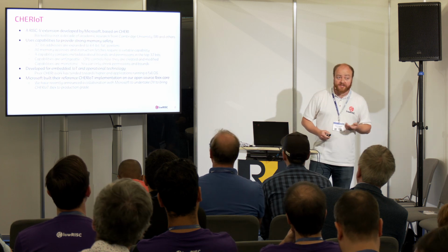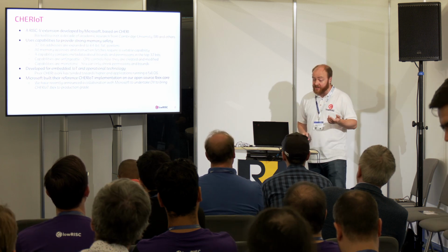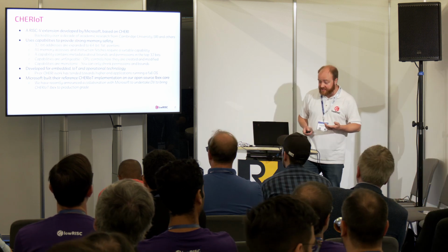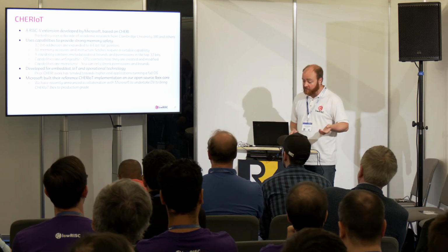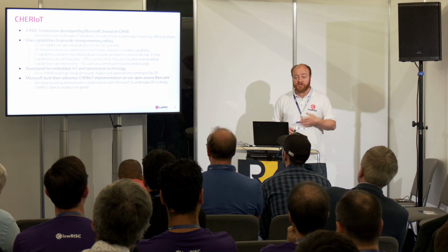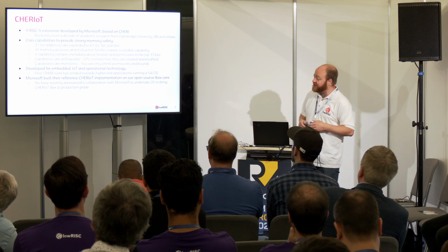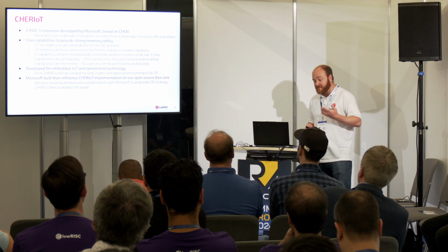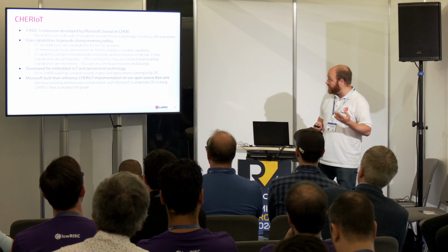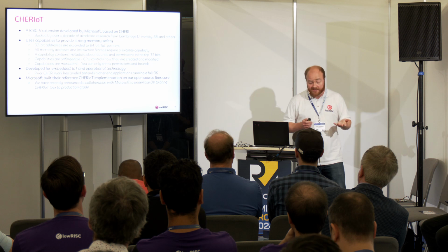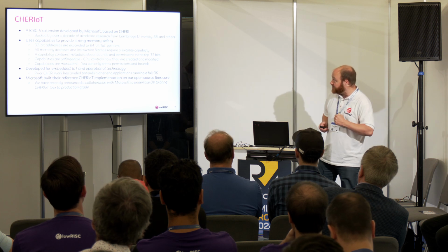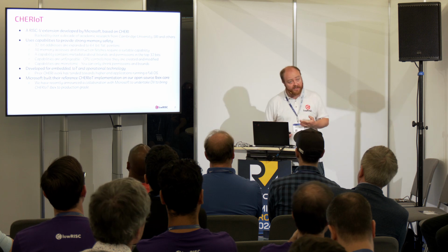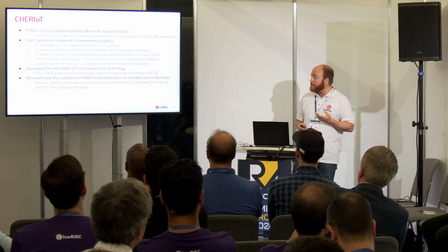So before I can tell you about Sonata, I need to tell you about CHERIoT. CHERIoT is effectively a RISC-V extension that has been developed by Microsoft, and it is based on the CHERI work that many of you may well have heard of, and it is backed by over a decade of academic research that was started off by Cambridge University and SRI International, and many others have worked on it since. And the core thing CHERI and CHERIoT gives you are things called capabilities.